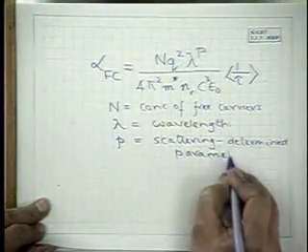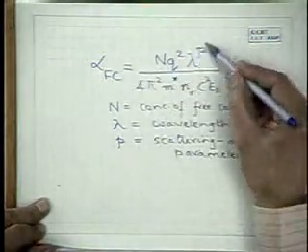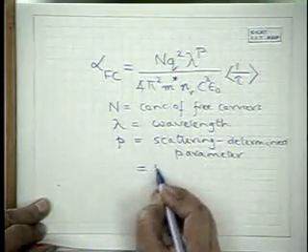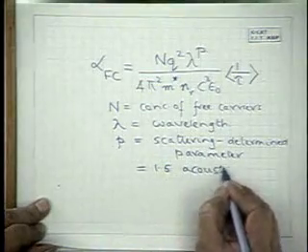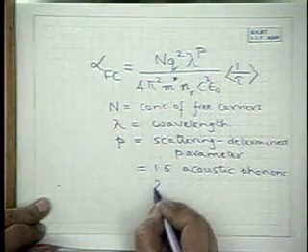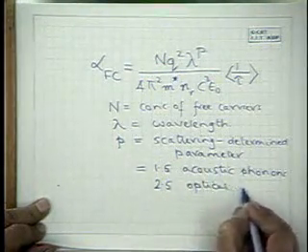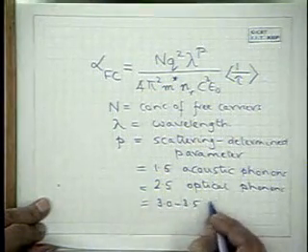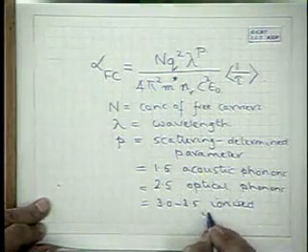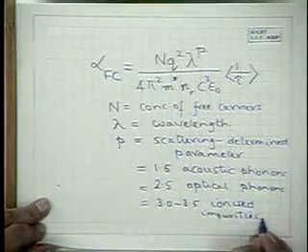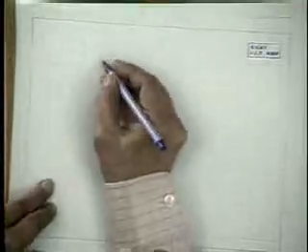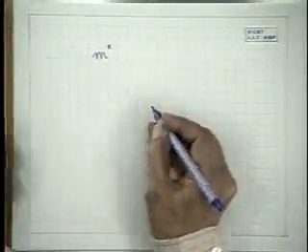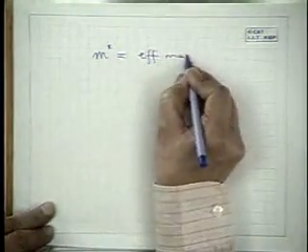In the case of the free electron theory as given by Drude, this free carrier absorption occurs and p is just equal to 2. But if you take into account the different scattering mechanisms, then p is equal to 1.5 for acoustic phonons, 2.5 for optical phonons, and 3 to 3.5 for ionized impurities. To continue describing the parameters, m star is the effective mass of the carrier involved.